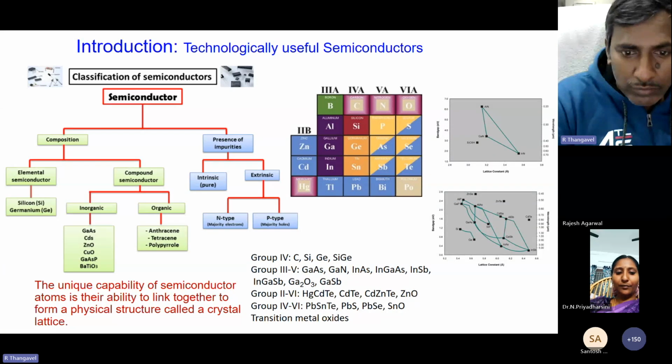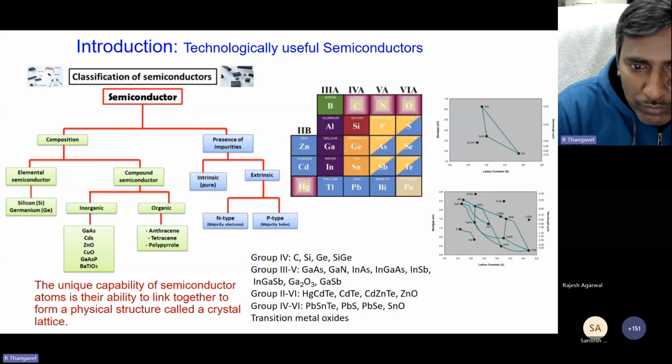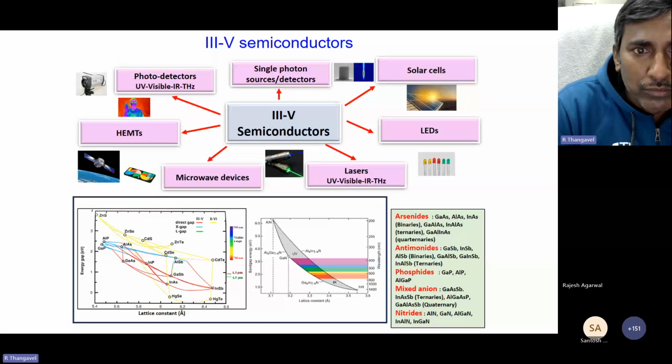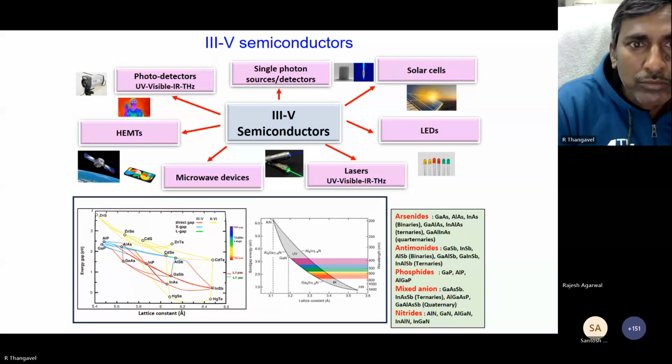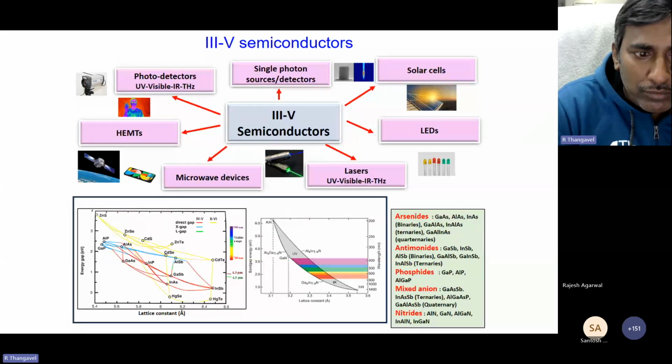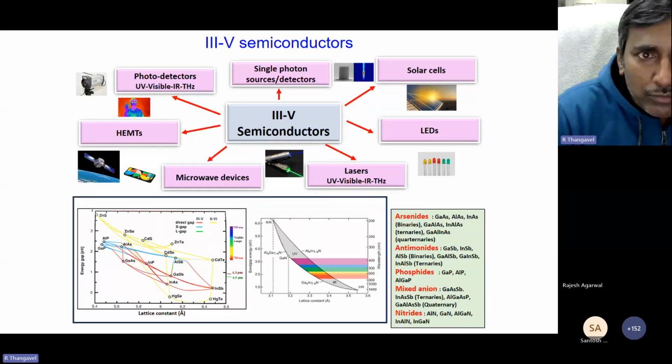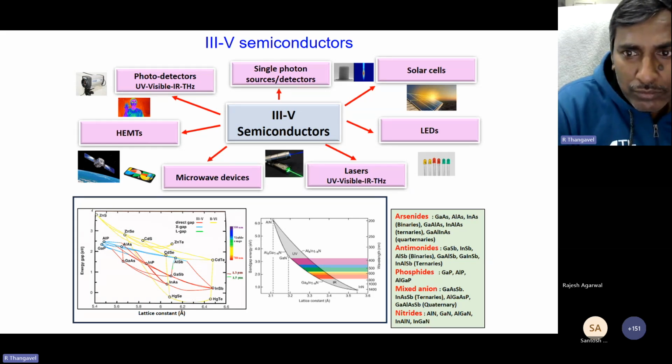And this is the energy versus lattice constant plot, where you can see how it is changing. Now, among the common semiconductors: silicon; 2-6 semiconductors, cadmium zinc telluride, mercury cadmium telluride, zinc telluride; 3-5 semiconductors, gallium arsenide, gallium antimonide, 3-nitrides. Right now, silicon carbide is also used for power device applications. Germanium is an IR semiconductor. There are also 2D semiconductors, graphene and MoS2, and metal oxide semiconductors.